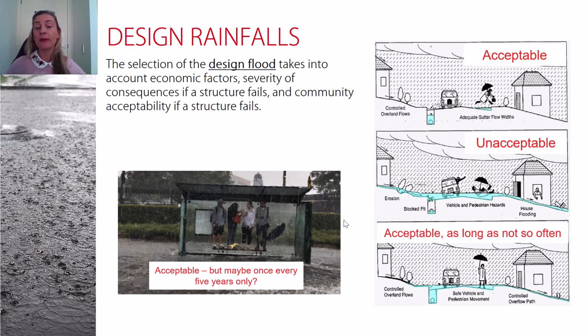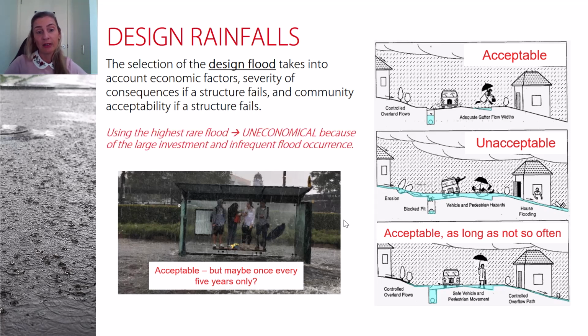So there is an optimum value for a design flood to be used in the design of the various systems that are part of the entire drainage network. And as I said before, using the highest rare flood could be uneconomical. This will incur large investment for infrequent flood occurrences.